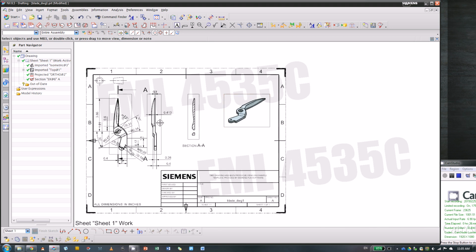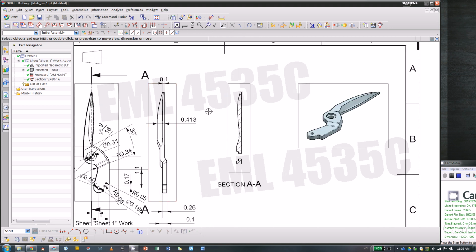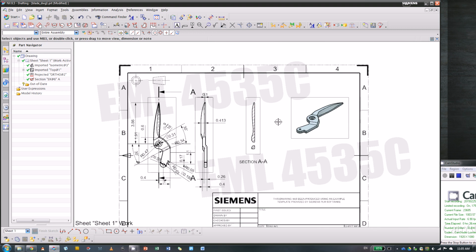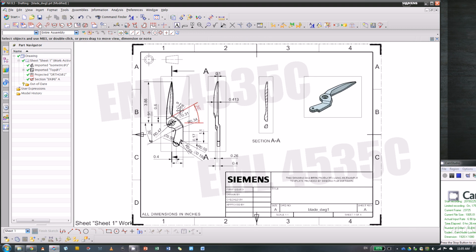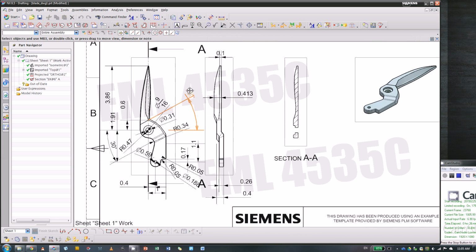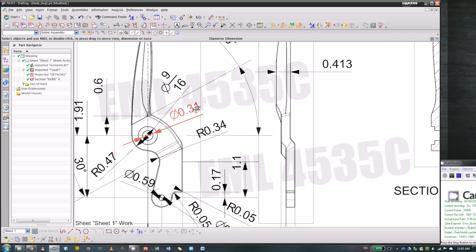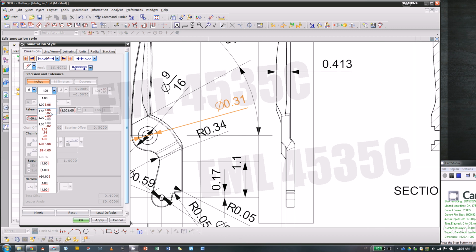So in the project we will ask for 2 views plus 1 section view with some dimensions. I know it's hard to properly dimension a part, especially if you don't have any experience in drafting. In the real thing, you would have tolerance on each of the dimensions. If you don't have tolerance, people don't know what you want for the machining.